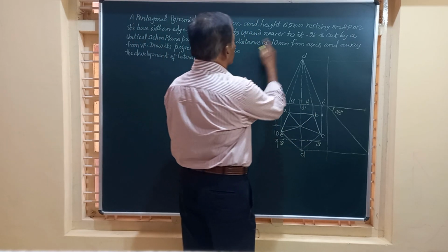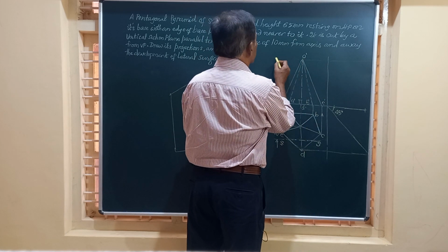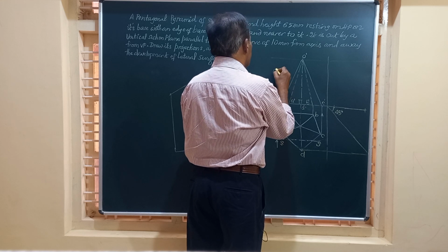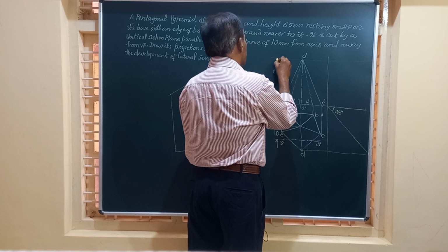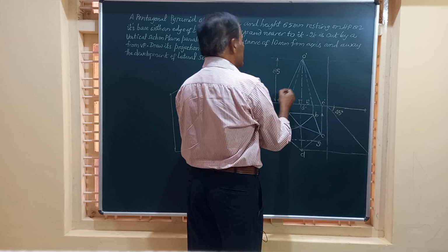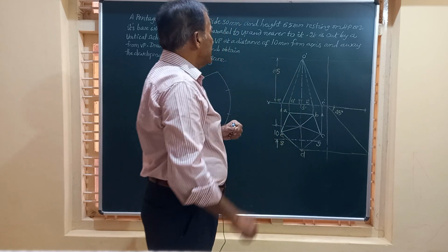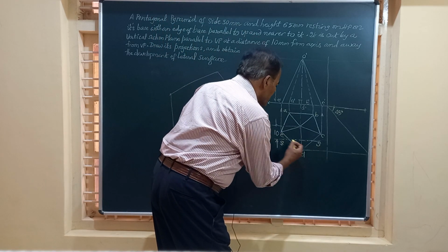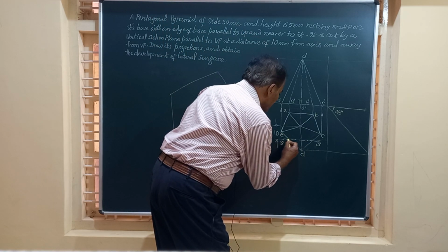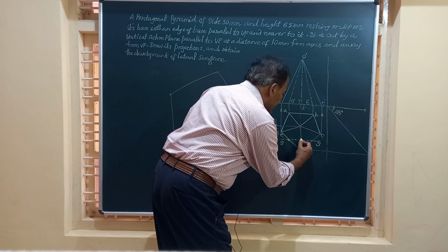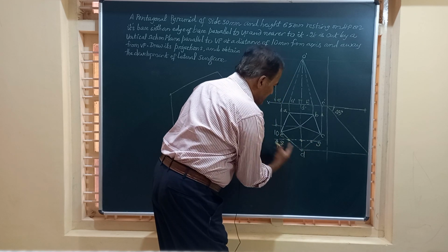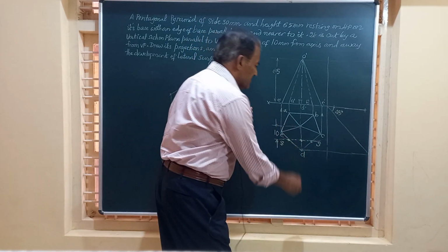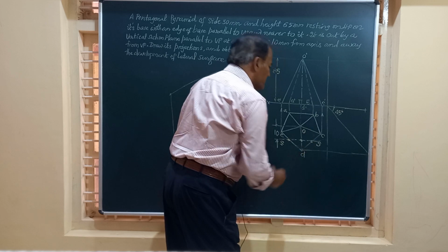Friends, the height of the solid what I had drawn here is of 65 millimeter height. 65. We have to show the dimension where the height is shown. And with this friends, the object is being cut by section plane like this. So at a distance of 10 millimeter from there, it is cutting the base edge DE, base edge CD and also the slant edge OD.